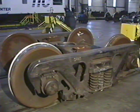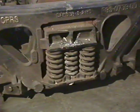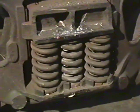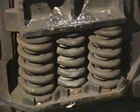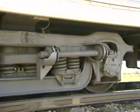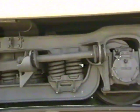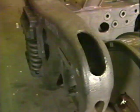Conventional freight car trucks include the bolster, two side frames, a suspension system, and the axle wheel sets. A freight truck suspension, like the one shown, typically uses friction or hydraulic damping in parallel with a coil spring arrangement to control the ride quality of a car. Passenger train suspensions typically utilize rubber pads, airbags or springs, and hydraulic dampers. Both passenger and freight cars are subject to rare conditions of vehicle-track interactions that may result in a derailment.